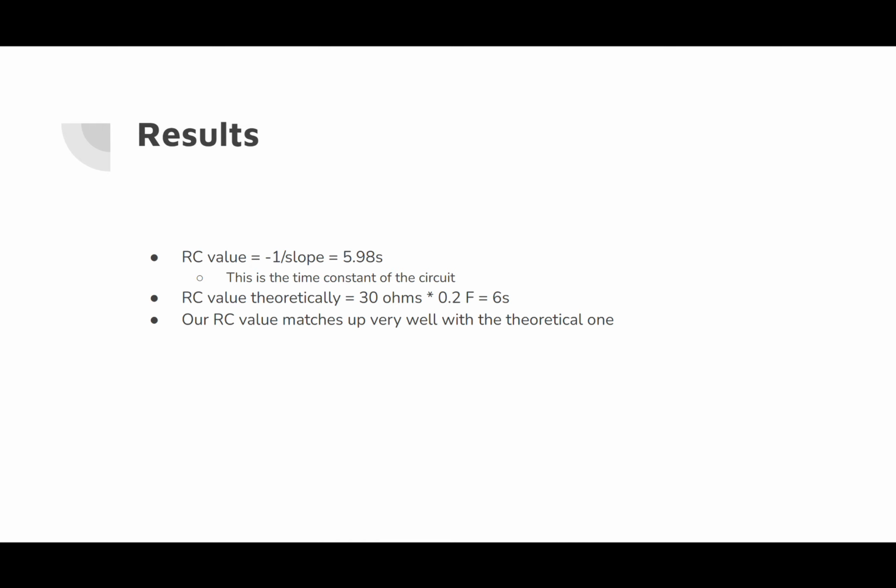So in order to get that, we got 5.98 seconds, and our theoretical value, if we take the resistance times the capacitance, we get 6 seconds. So our RC value experimentally matches up very well with our theoretical one.